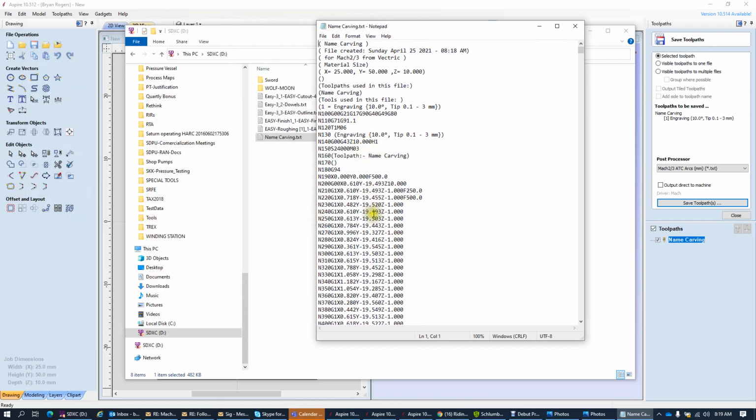And this is the G code, point by point. The interesting thing that I want to show you here is this command right here. This command says that's the home position. And the very first command is to go to Z10, okay? So that's 10 millimeters off the top. It's going to go to Z10, and then it's going to go to the start point of your name. There's the start point of your name, okay?